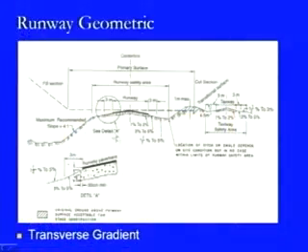Here we are looking at another diagram where we show the same sort of condition, where the runway is provided here as a thicker black line, and this runway strip is provided with 1 to 2% grades in the two directions with respect to the center line.